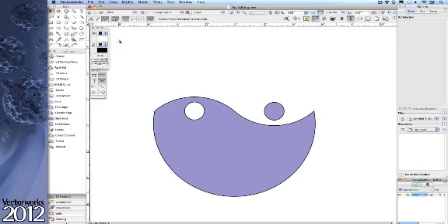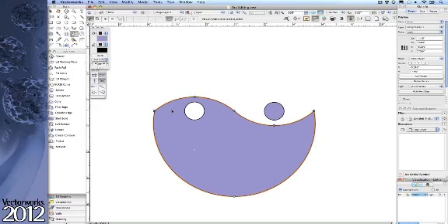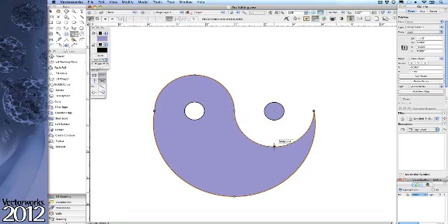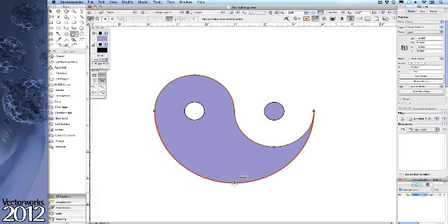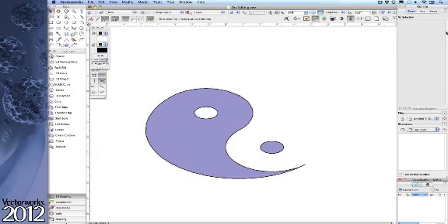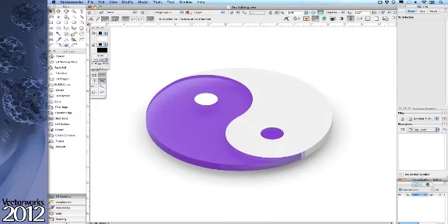And while we're reshaping things, check this out. At first, this operation might seem like no big deal, but notice a couple of things. There are fewer vertex points in this shape. This is because they are now radius vertices and can be reshaped accordingly, offering a much more fluid and predictable reshaping of the element. These radius vertices can be converted back to arc vertices in the Object Info palette if that need arises.